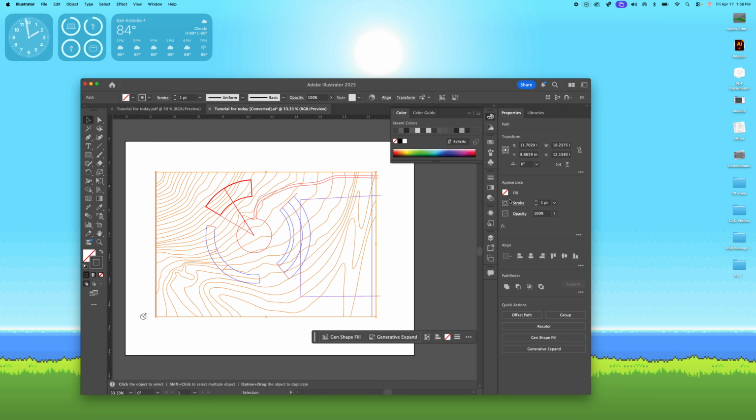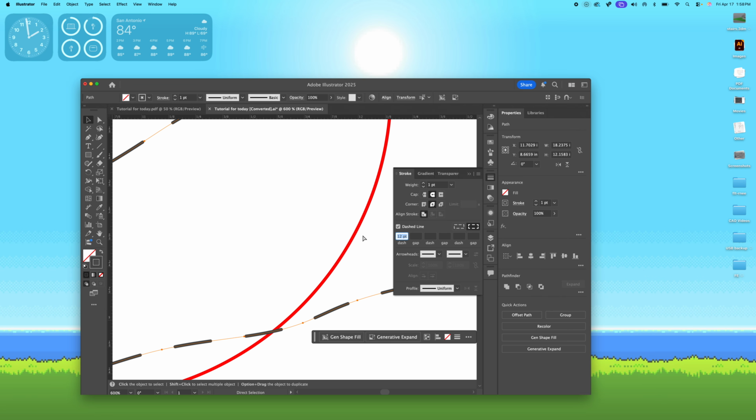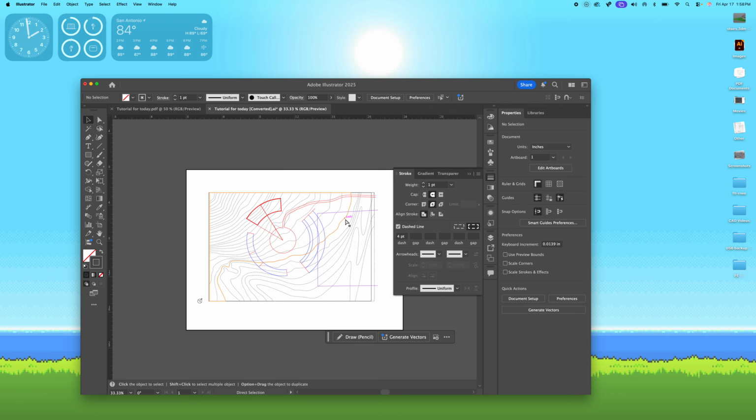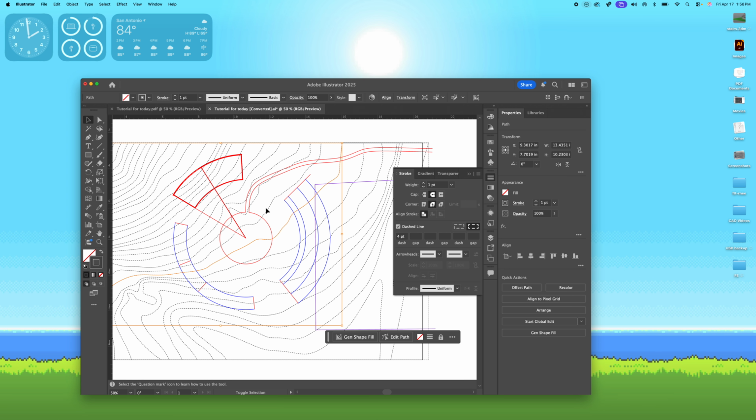As you guys know or may not know, most of the time topography in site plans is dashed. So if you go to Stroke and you go to some more advanced settings in Stroke, show options, you can actually select a dash line. And in our case, you can actually get pretty darn close. I typically choose about a 3 or a 4. And voila.